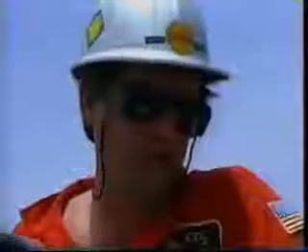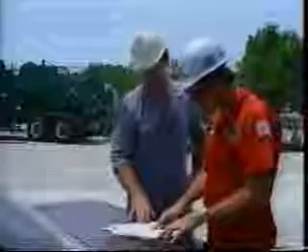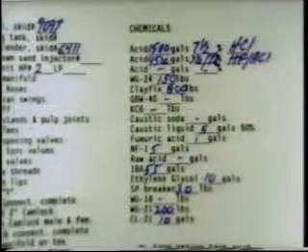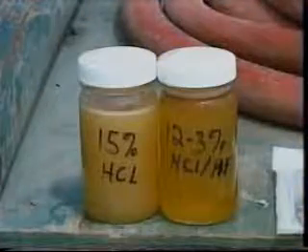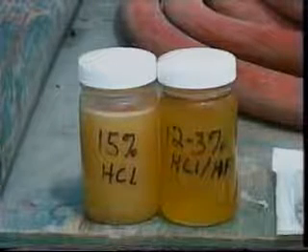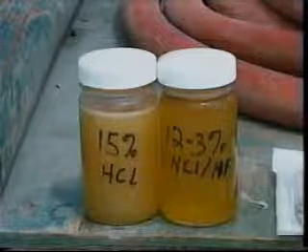The engineer should review the service company's call sheet to ensure that all the necessary additives are available on location in the correct quantities. Certain additives must be mixed on location. Others can be mixed at any time. After the acid tanks have been thoroughly mixed, the engineer must be sure that the concentration of the HCl acid is checked in order to confirm that it falls within design parameters. This is done, preferably, with a titration kit, but it can also be performed with a hydrometer.